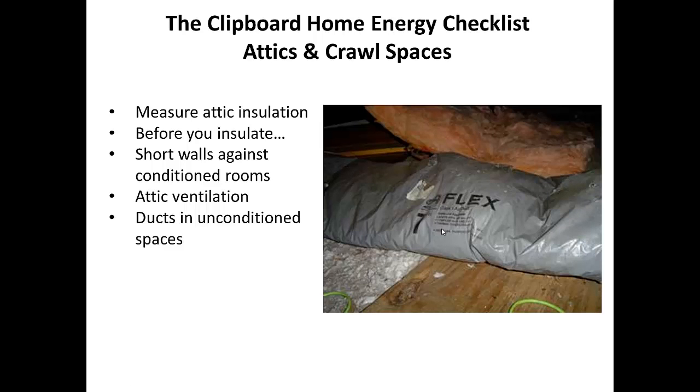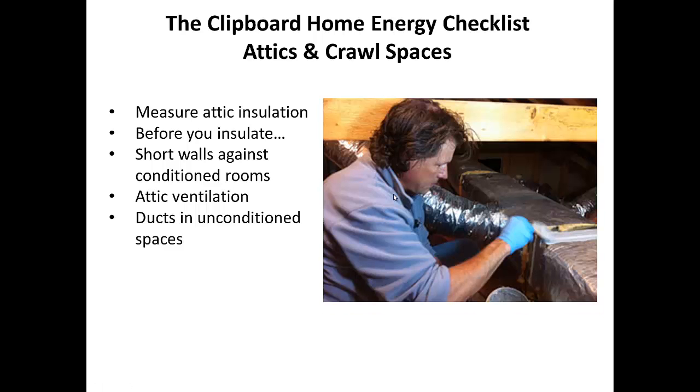Another thing to look for is the ductwork in your attic space where it's been trampled on over time. Somebody got up there, a contractor or a homeowner, and stepped on it. So the room that's being supplied by this flex duct is not getting its fair share of energy right now. And so what you can use is silver tape to get in there and shore up some of these areas.